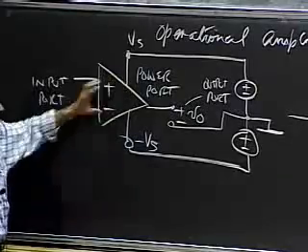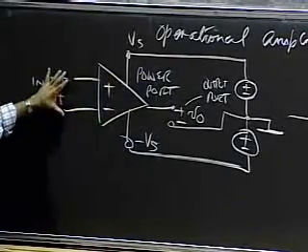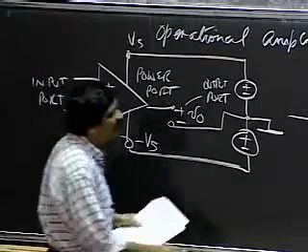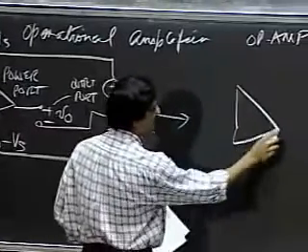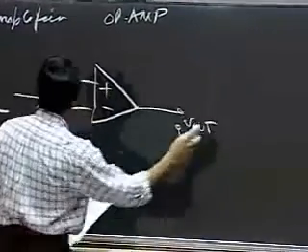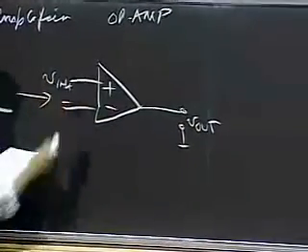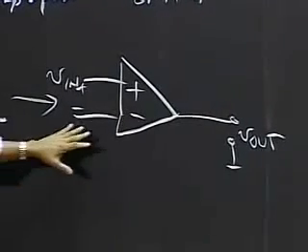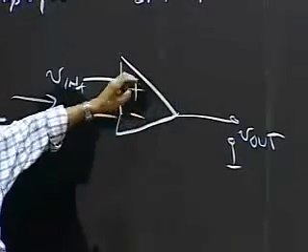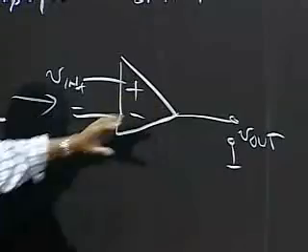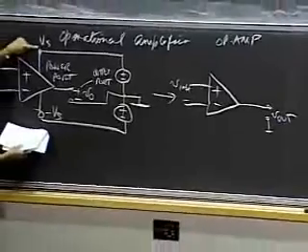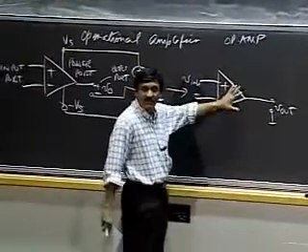So this is an abstract differential input amplifier. In other words, this amplifier is going to amplify whatever I apply at the input. So a slightly more abstract representation of this looks like this. V out and plus minus V in. Okay, this is a slightly more abstract representation where, remember, we're going to draw this again and again, maybe at least 38 or 39 times in this course. And remember, each time we draw it, there is an implicit power port, a plus minus supply that is connected, which we don't show.